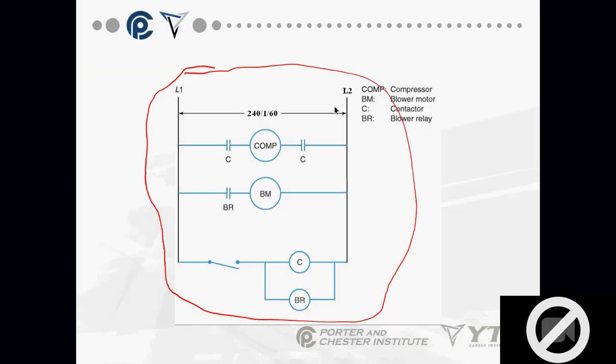This is a window unit. Doesn't it? This would be a thermostat over here. If I take this and make it into a cooling thermostat right there, it closes on temperature rise and energizes a contactor coil.